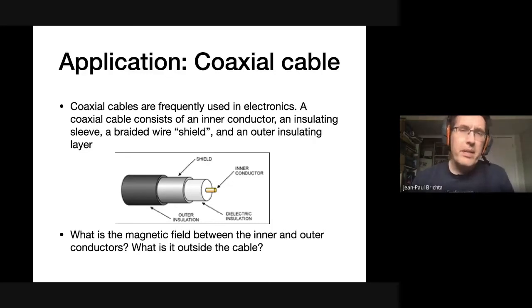You could imagine that if one coaxial cable was next to another, and they each had electronic signals, if they had a large magnetic field, one cable could make noise in the next. So that was part of the reason why we used coaxial cables as opposed to regular old single conductor cables.